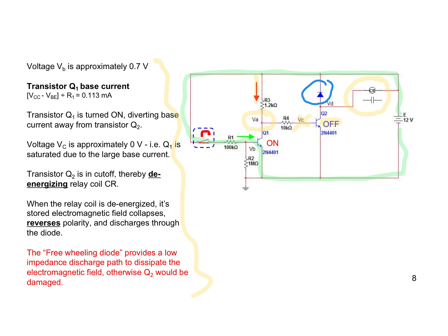That stored electromagnetic energy needs to be dissipated, needs to go somewhere. So we know by Lenz's law, when that field collapses, it will flip reverse polarity, and therefore we have a current path down like that to bleed off the energy from the coil through that power diode.